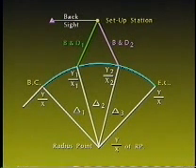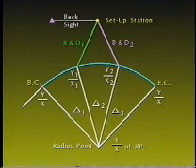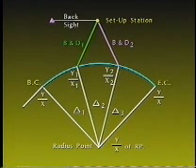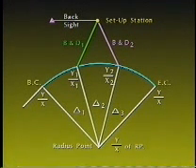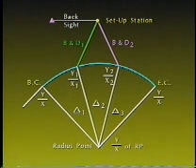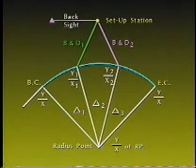With all elements of the curve located on the coordinate system, calculations for the curve data and also the actual layout are reduced to routine inverse calculations. This provides stakeout data for bearing and distance layout of all required curve points using a single setup location. In practice, the setup point is selected and tied to the curve's control system, either in the field by actual measurement or by office calculation. As shown in this graphic, the BC, RP, EC, and setup stations all have coordinate values.